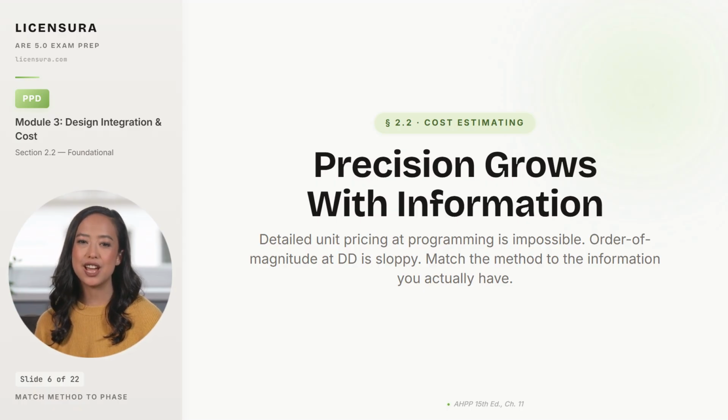Cost estimating is not one technique. It is 4 different techniques matched to 4 different phases, each calibrated to the information available at that point in design. Precision grows with information, not with owner pressure. The architect who quotes a hard number at SD without disclosing the plus or minus 25% range is the architect who gets sued when bids come in 20% high. And the exam will fail you on a question that hands you a phase mismatched estimate if you do not flag it as the trap.